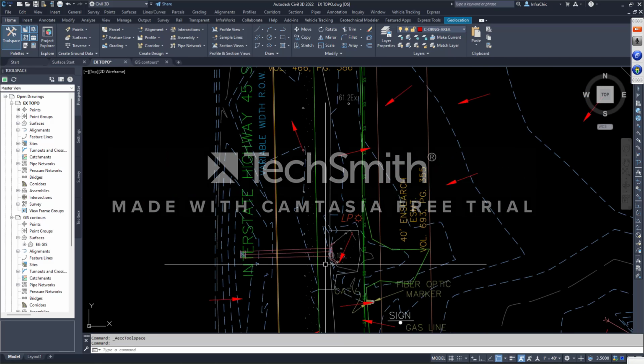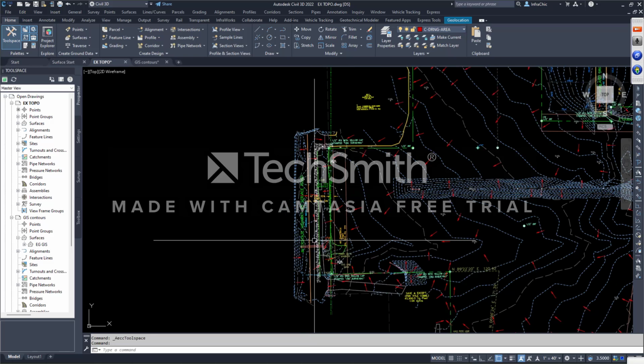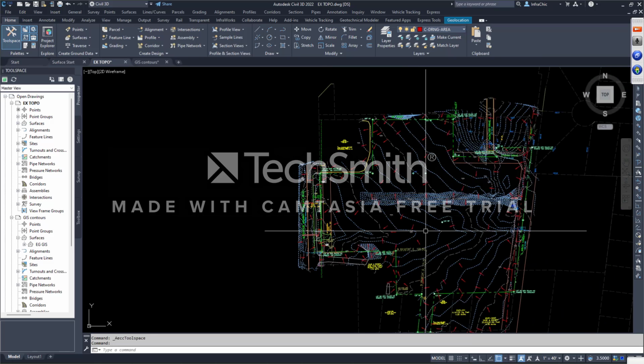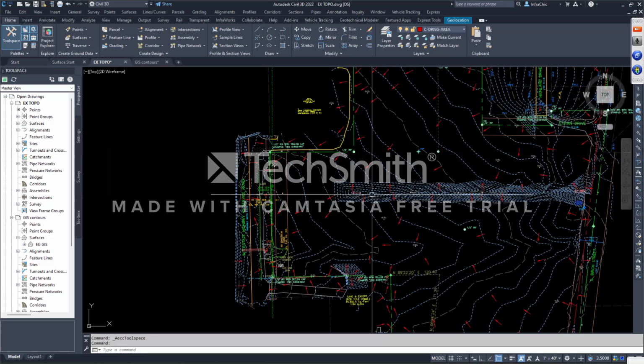Whereas over here, we have a head wall, we have a pipe, and we have an exit point. So that tells me that, yeah, we got that. Photos can speak volumes, and I cannot stress that enough. When your guys are in the field, running that rod and total station or the GPS unit, ask them for pictures. I need pictures of stuff so that I know, is this hill really a hill where I'm looking, or is that an error? Because if that's an error, you won't know that without a photo, right?